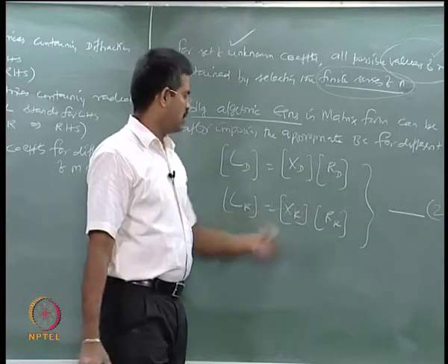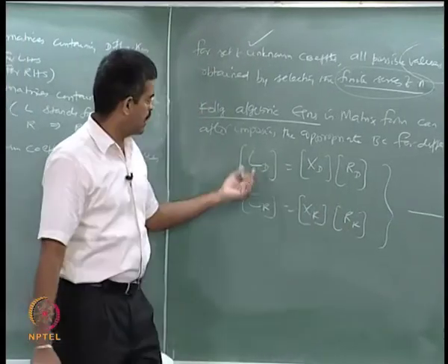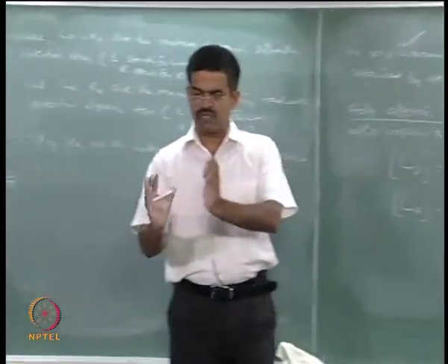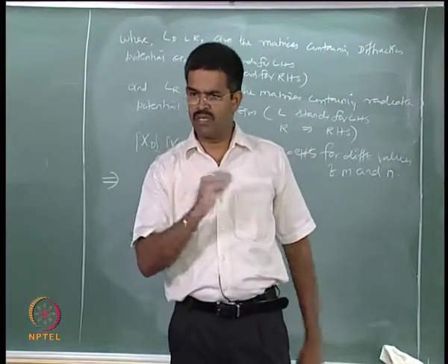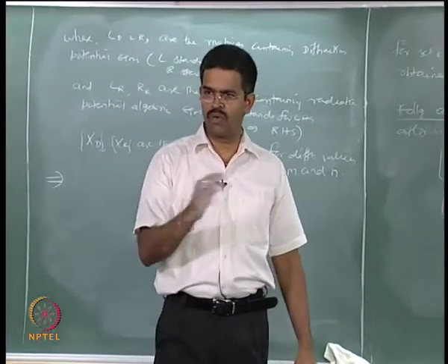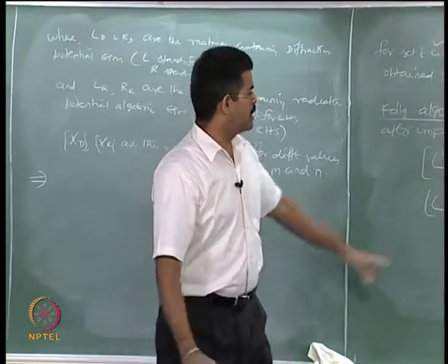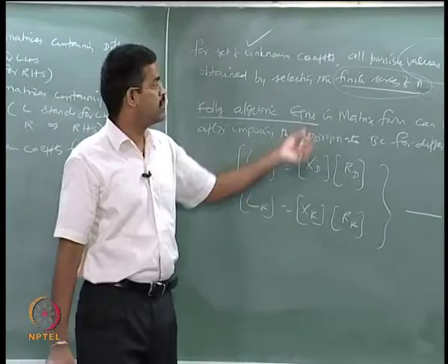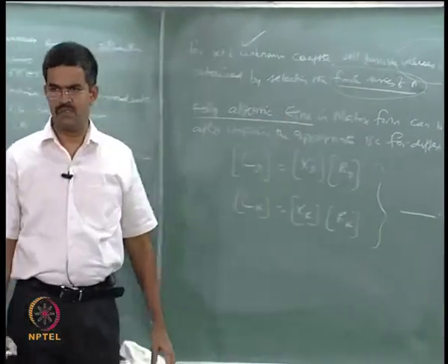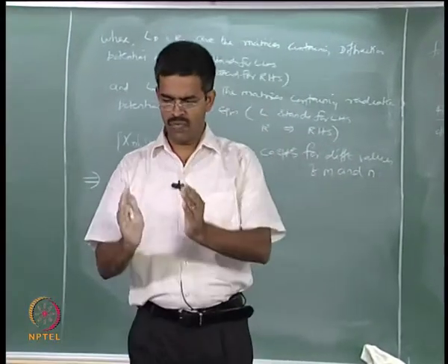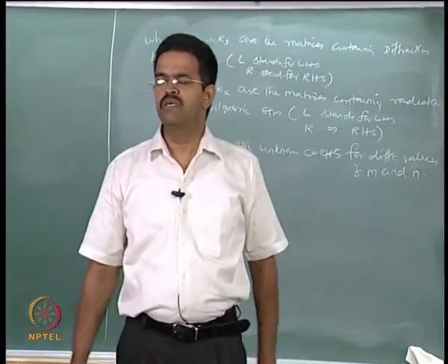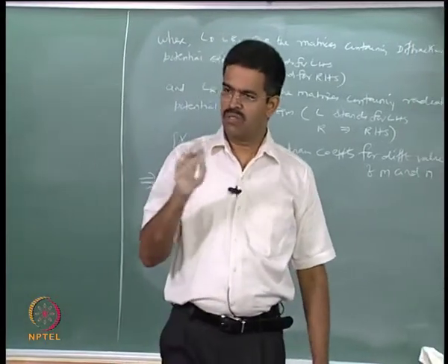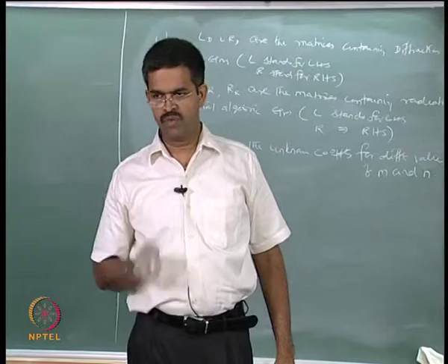LD inverse of RD and LR inverse of RR. LD and LR, RD and RR will be the series of terms which you get from equations 17 and 20 after substituting their respective boundary conditions, and you will get the vectors XD and XR solved automatically for different m's and n's in the series. So, now you will be able to get for the defined regions 1, 2 and 3 the diffraction potential and radiation potential in all the 3 regions independently.